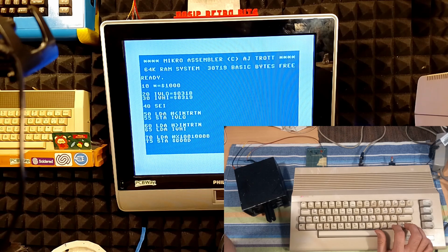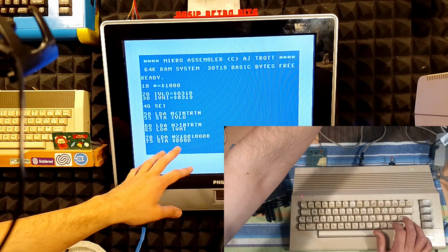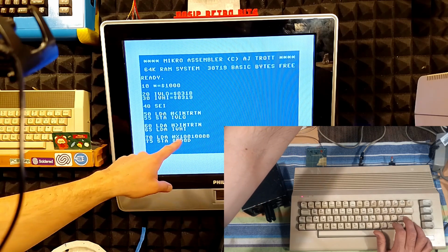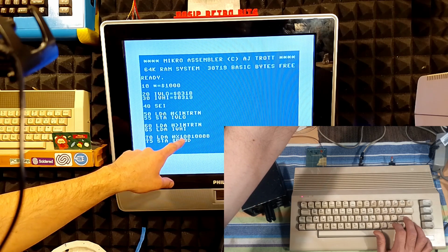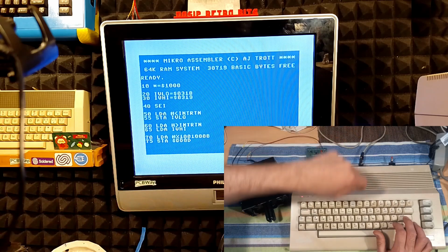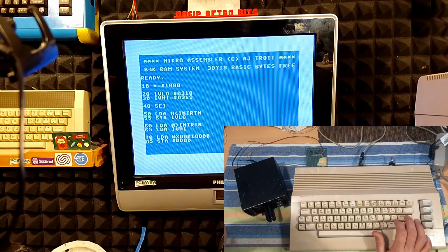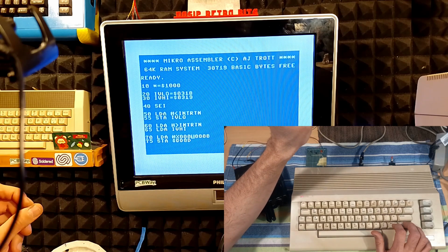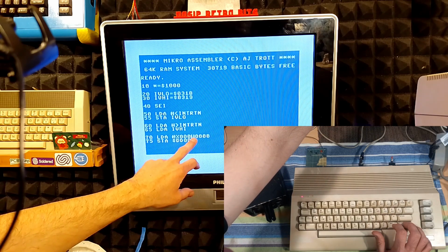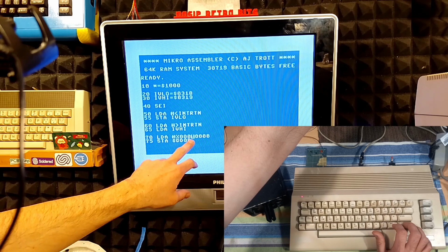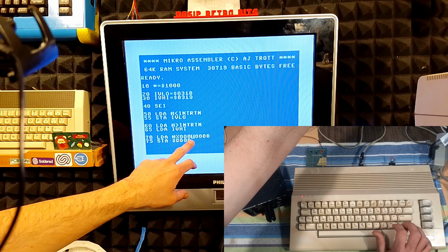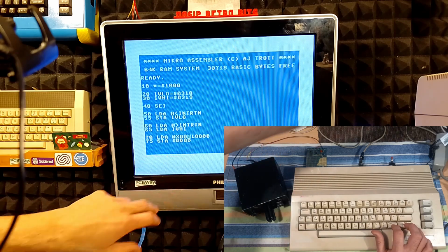In case we want to stop or disable this interrupt, instead of 1 at bit 7, we need to specify 0, but we have to leave the 1 here, and this value will then disable this interrupt.